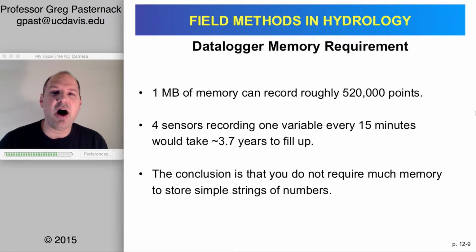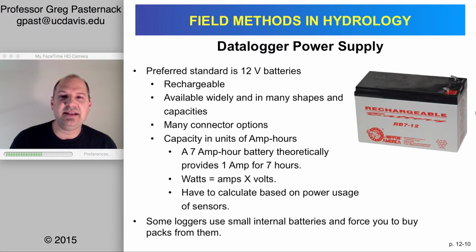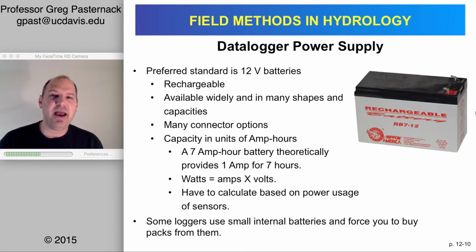It also depends on how often you're going to go out, and I certainly wouldn't recommend leaving a data logger there for 4 years and never going. I mean, that wouldn't fly anyway. But in general, memory is not the limiting constraint. Instead, it tends to be power. Data loggers don't necessarily require a lot of power, but they definitely require power, and in my experience, it is power that limits how long a data logger can sit. And in some ways, that's not all bad because, again, it's good to go out and see the data, see the site, maintain equipment, keep things operational.